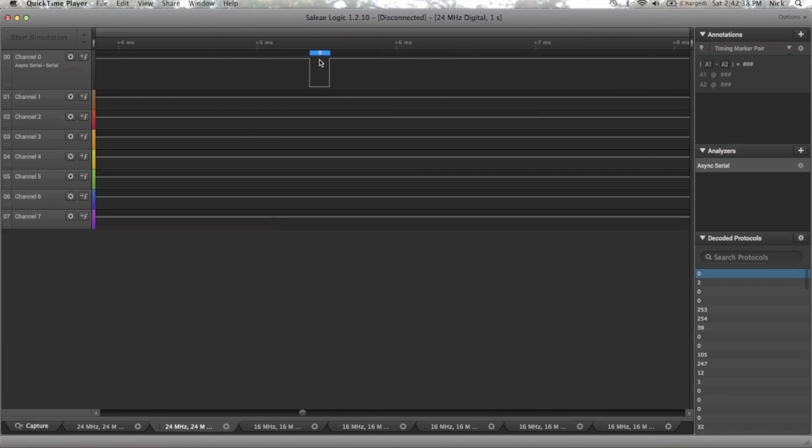So you can actually set up the baud rate so it reads the bytes properly. So it'll tell you in decimal what each byte is. And if you zoom in, you can see each part. So you got 0, 0, 0, 0, 0, 1, 0, 0, and then that's the end. This start one, when it first goes low, is the initial start bit, and the stop bit is just part of the idle stream. It's just as long as it needs to be.